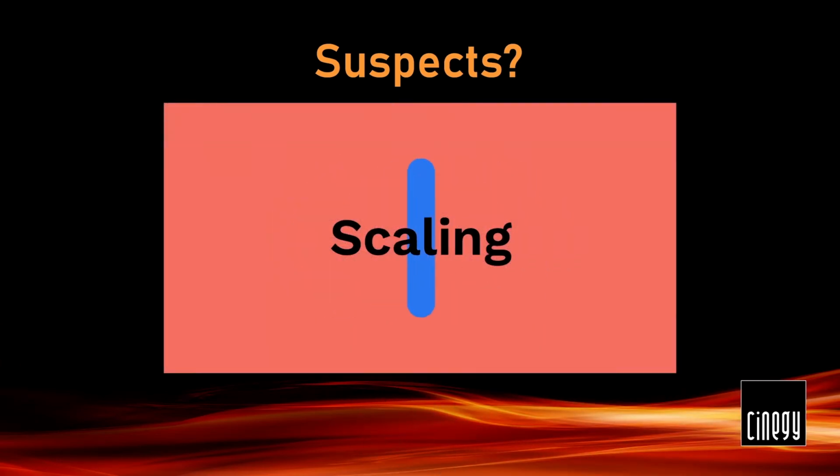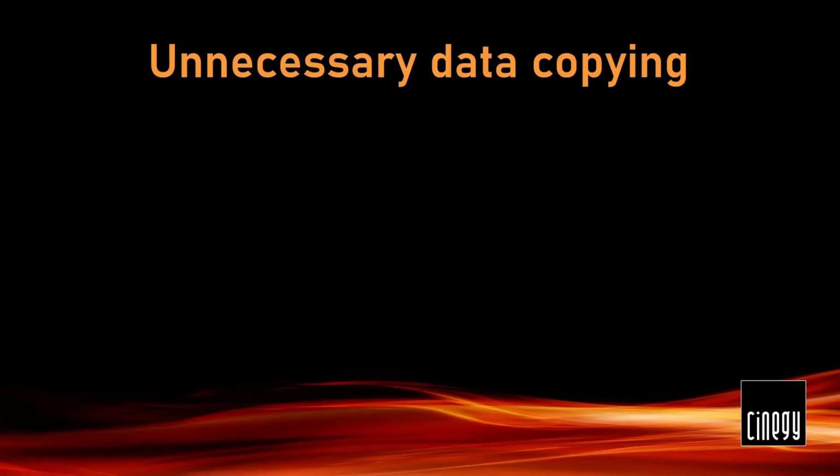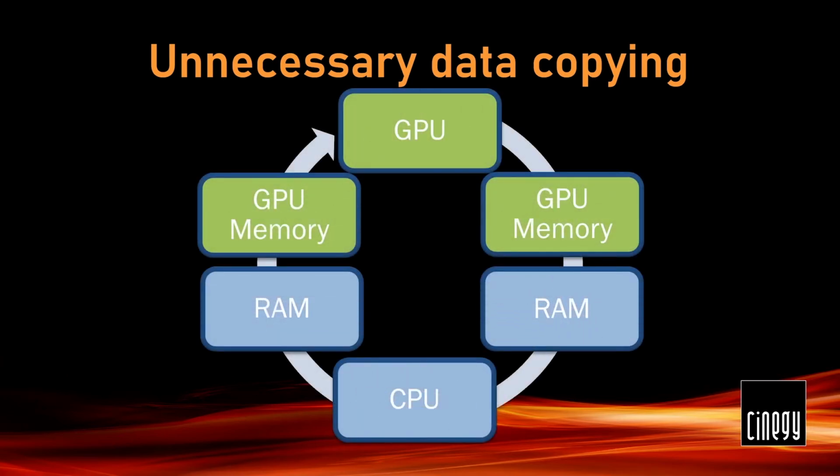During the video frame processing required for scaling, the GPU would decode an uncompressed video frame of 4 megabytes of data for full HD. This data goes through a number of copying cycles from GPU to RAM, then to the CPU, just to be passed back to the CUDA cores of our GPU's main chip for processing. The main idea around improvements was about reducing the amount of these data copying operations and concentrating data processing in Multiviewer's master GPU pipeline.